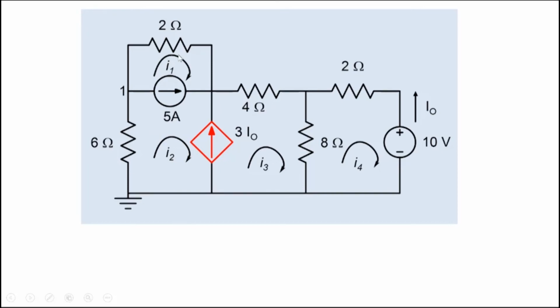Now in this case, if I combine these two meshes, I solve the problem of not knowing the voltage across this particular one. But I still have, when I try to write KVL, what will I write as the voltage drop across this current source? So this is still a problem. So what we can do is super meshes, not just two meshes combined together, but you can combine three meshes here. So we can combine these three meshes together and write it as a super mesh. So basically then we have two KVLs to write, one for this and one for this super mesh.